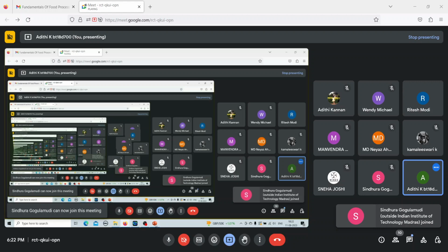Here, one thing I need to mention, here N naught is different. This is not at 121 degrees Celsius. This is just the initial concentration. All other values like temperature, D value and all, the moment you have a naught, it basically means 121 degrees Celsius. In this case, this naught is different. This is just for the initial concentration. If you want, you can make it as NF and NI. It's up to you guys. So don't get confused between this naught and the naught that we've been discussing so far.